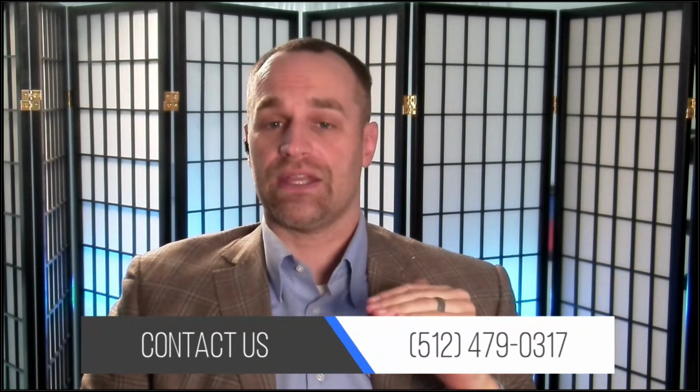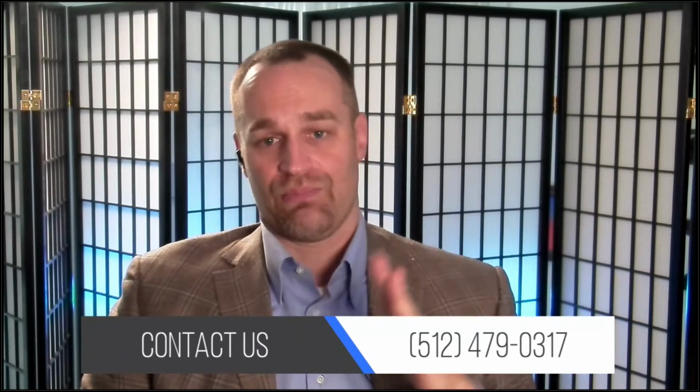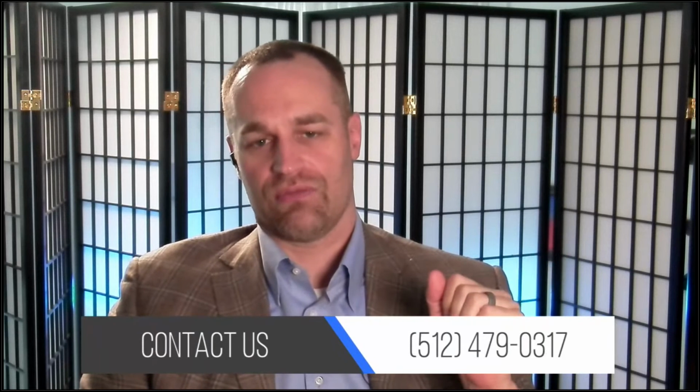Great question. Like I mentioned in the presentation, if you're dealing with 24-volt passive PoE, it's always got to be mode B. If you're dealing with IEEE standard PoE devices, mode A is fairly universal. And if you just really don't know, we can also supply mode A, B products, so you would get power in mode A or B, and then you don't even have to care. But the note here is you have to have 24-volt power if you're going with a 24-volt passive device. So in that case, it would still be mode B, but you have to be 24-volt on mode B.